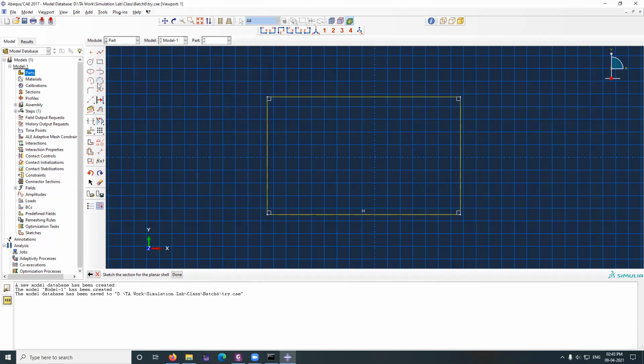There is something here called dimension. Add dimension. Say, for example, this is of some other value. If I now add dimension, I can change this particular length. Let me click this one, click this, drag it and click this. Whatever length I created by default is nothing but 3 mm. You can see it, right? 0.003 is nothing but 3 mm.